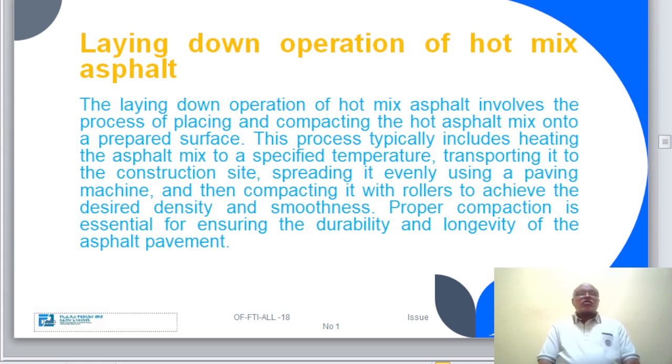Finally, pavers that can simultaneously lay two asphalt layers in a single pass have been developed. This results in better interlocking of the courses, elimination of tack coating, and reduction of the paving time. The method is known as the compact asphalt laying method.